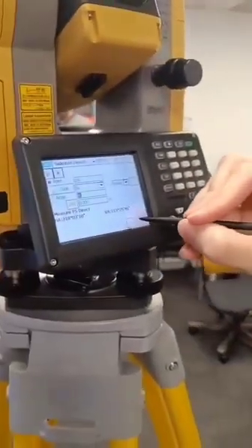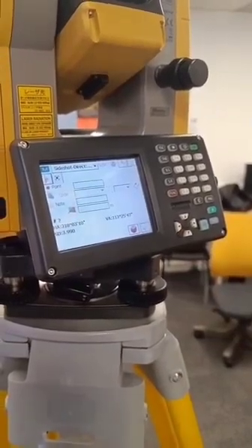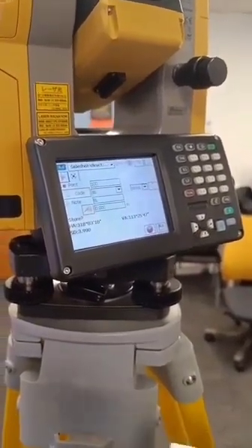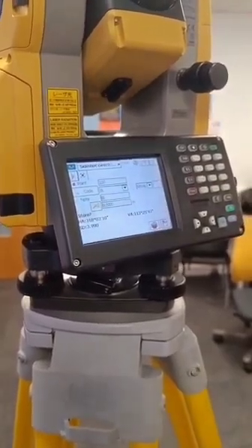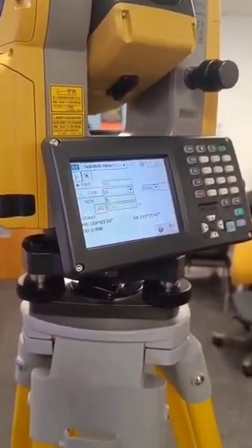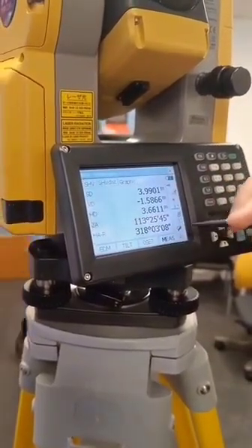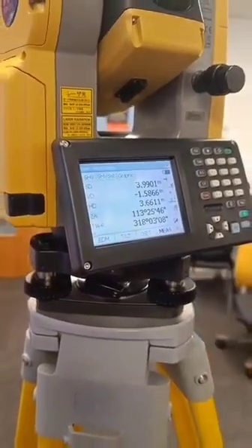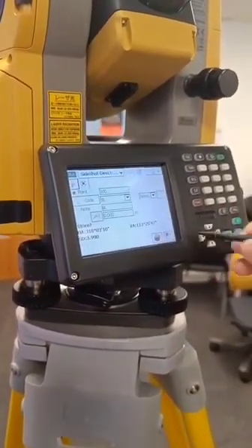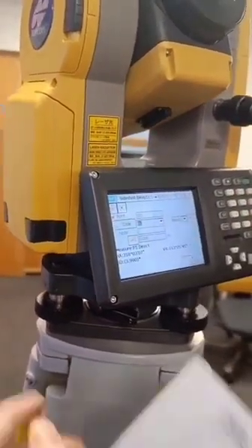I'm just going to hit this button on the left, not the one on the right. That button is to take a measurement without saving it, so that you can go and edit anything you need to. Like if you realize you used the wrong code by writing it down, you can be like, oh, I'm going to quickly change that. And if you hit PRG again, you can switch back to this menu, and it has all your measurements that you need to be writing down. Always write them down after every one, and then just pop back in, hit save. So now it's automatically updated to 101. I'm going to move it to do the top left corner instead of the bottom left.